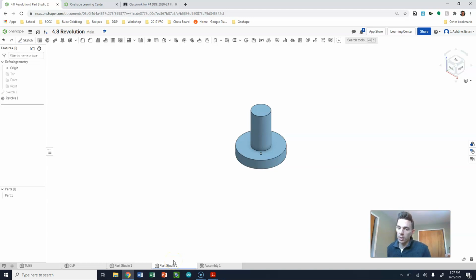And later on, we can use this to do a lot of drawings. And again, although sometimes it might be simpler to just use the extrude tool, other times it's much simpler just to use the revolve tool. You can get a lot done in one step with the revolve tool, where sometimes it takes more steps with the extrusion tool. And more importantly, there will be objects, like if we were to draw a donut, which can't be drawn any other way but to revolve. Same thing with the sphere. There's literally no other way to draw a sphere than to use the revolve tool.